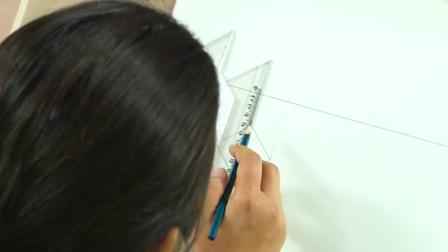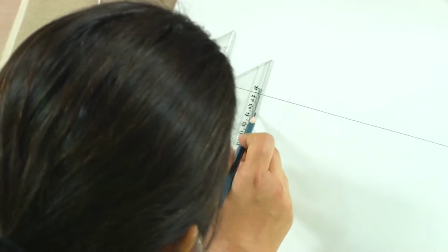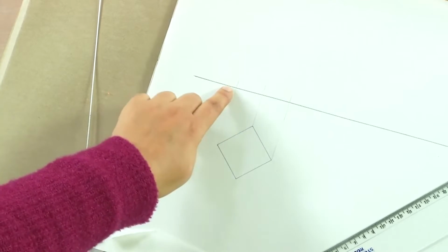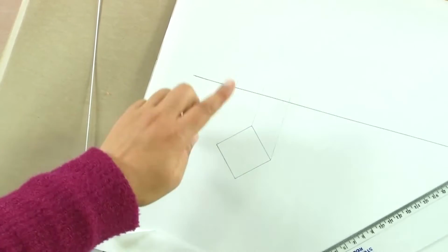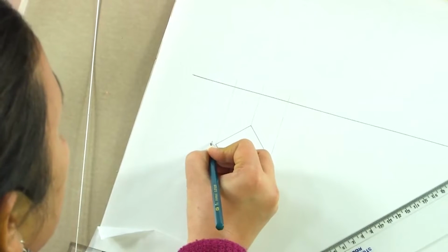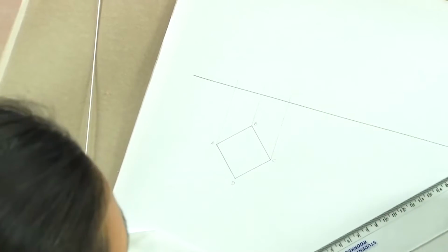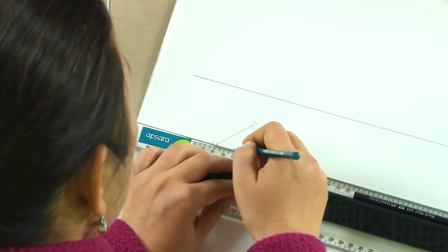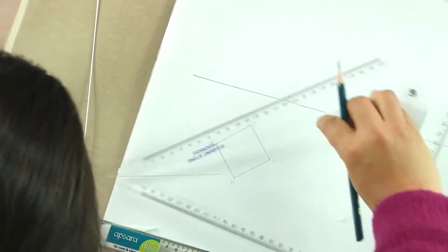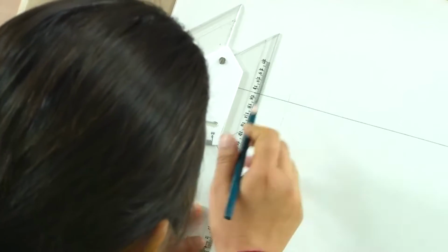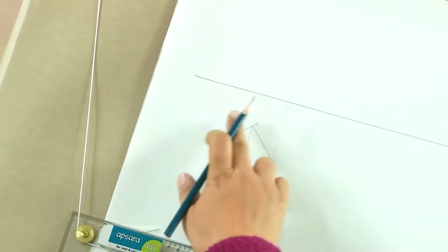So, this is not the final given condition, it is just the starting assumption that the plane is parallel to HP and it is perpendicular to VP. So, this is what we are seeing. I am very lightly labeling the square to start with. So, this is the square ABCD, and I will also draw the diagonals. So, we are saying that AC is the diagonal and BD is another diagonal. So, this is what we are going to be drawing.